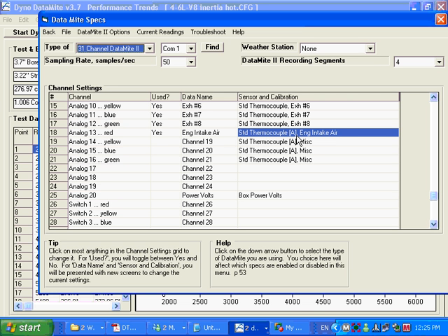I've seen it when I worked at Ford Dyno. We had everything in very controlled conditions. You pull an engine apart and put it back together, and it can be slightly different. So you want to make sure when it's a critical comparison that you do several tests, check for repeatability, and go back and forth between the modifications. And I know with a cam that's difficult to do, but if you need the answer, it is the only way to make sure.